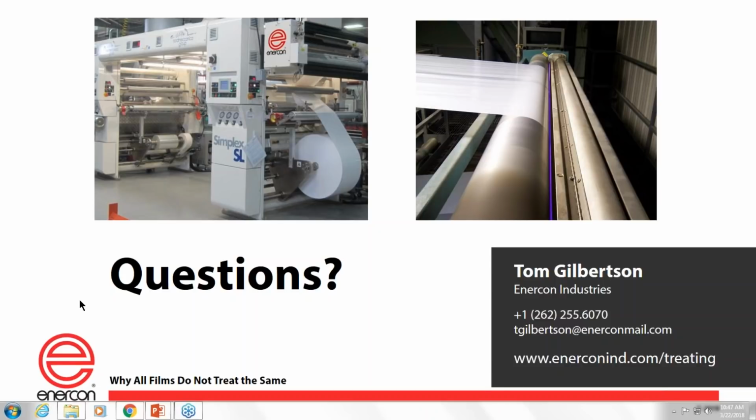How do you control backside treatment? Backside treatment is a common malady in our industry. It's one of the most commonly asked questions I get, and it's the simplest thing to solve. First of all, you have to know what it is. Backside treatment is simply ionized air behind the web. So for whatever reason, whether you have a bag in the film, whether you got dirt on the ground roll, whether you have a loose web tension, whatever the reason, you got air beneath the web, air between the back of the web and the ground roll. And when that air gets under the corona treatment, you're going to ionize that air, like we learned earlier. Corona is just ionized air.